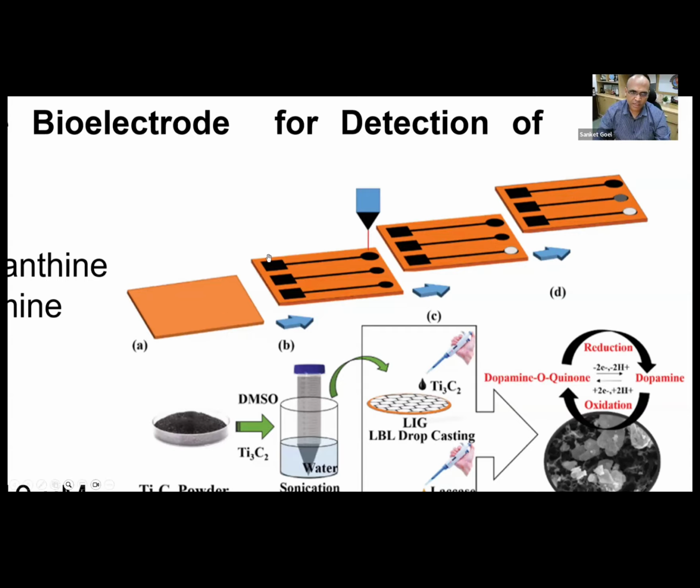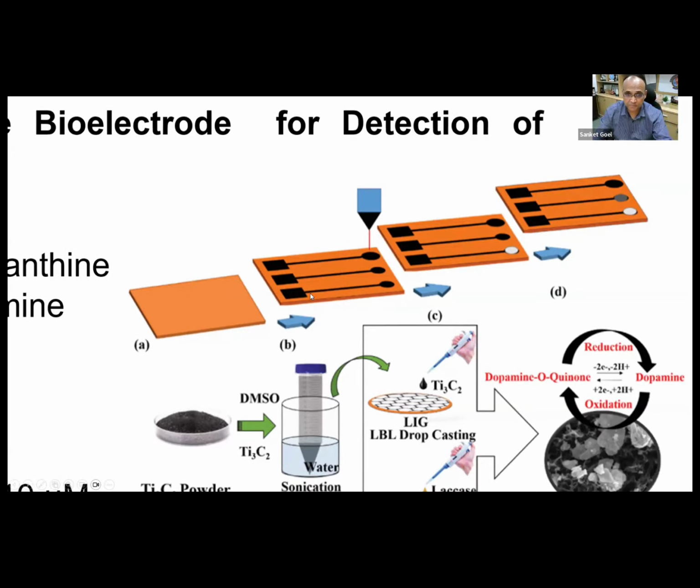So you can see that depending on the software, I can write some lines here. This is my polyimide sheet, which has the sp2 hybridization stage, and the laser can convert these stages to sp3, and then that will help me ensure that we can create a few layers of graphene, which will be quite predominant in terms of the conductivity.